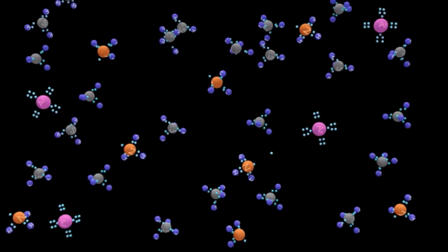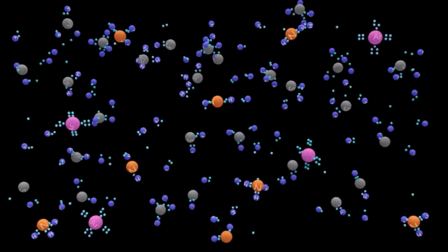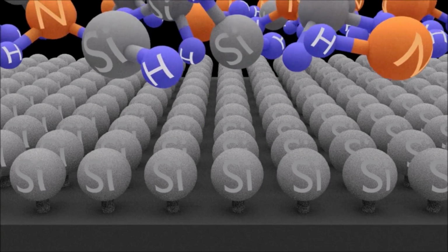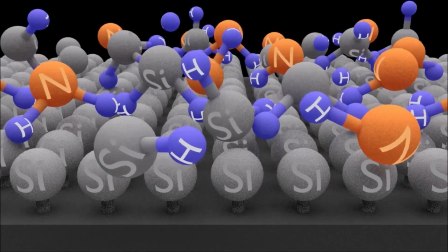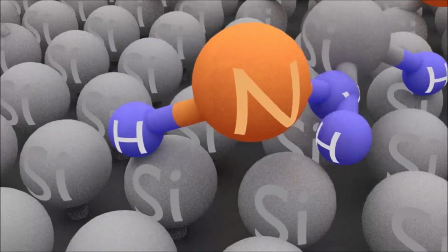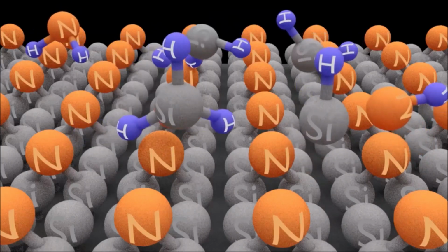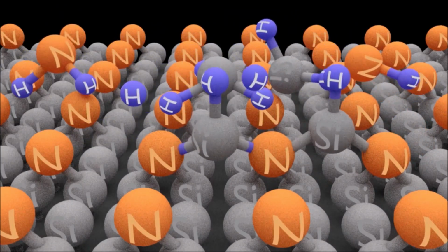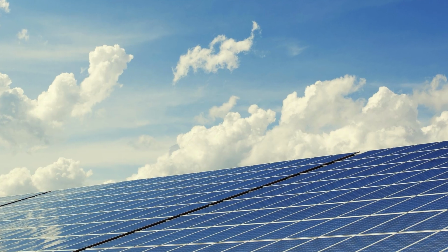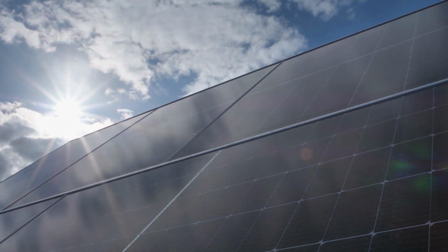Before the electrical current can be efficiently extracted, another major problem must be solved: reflection. In fact, bare silicon reflects a significant portion of incoming light. In order to reduce these optical losses, manufacturers deposit an ultra-thin anti-reflection coating, which is commonly made from silicon nitride. This layer reduces reflection, traps more light inside the cell, and therefore increases photon absorption. The characteristic dark blue or black appearance of modern solar cells comes largely from this coating.